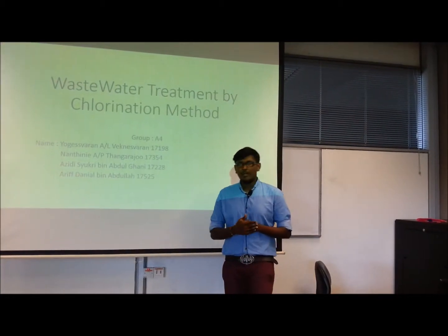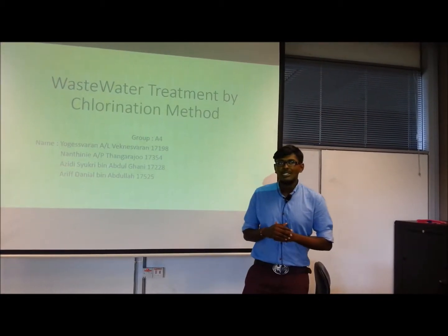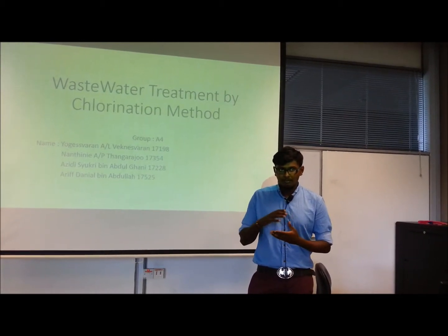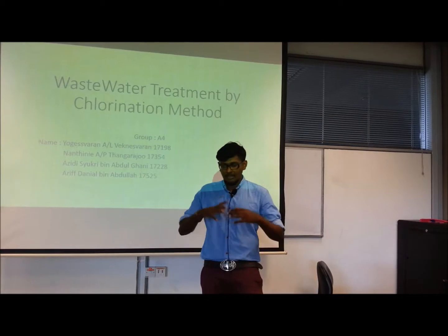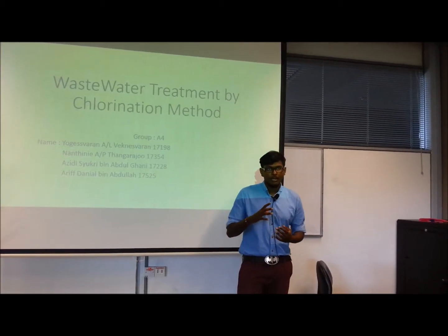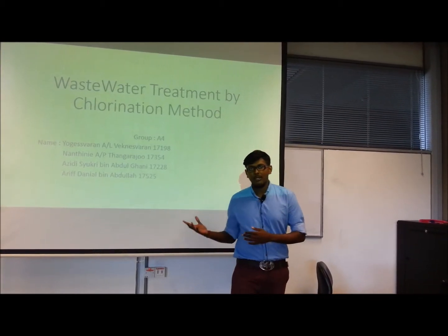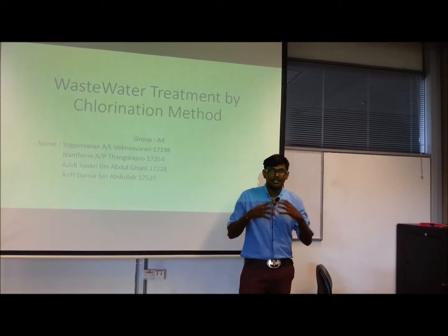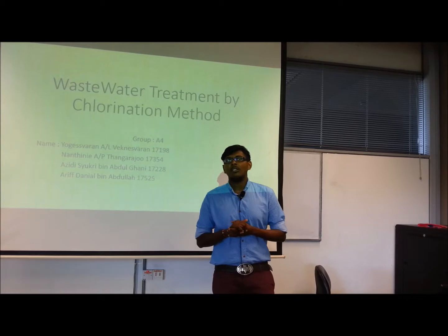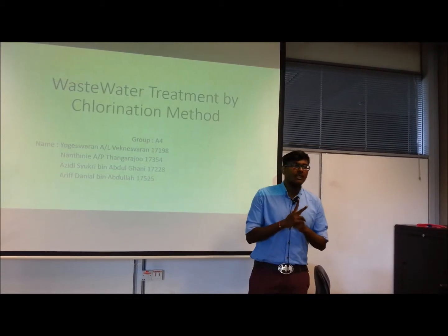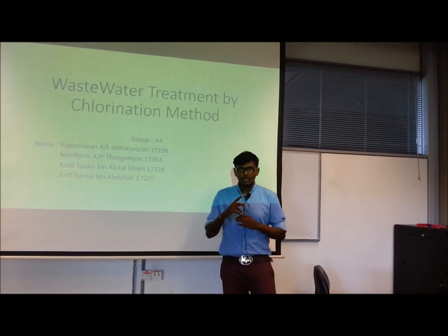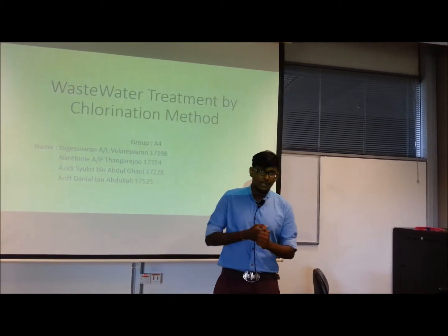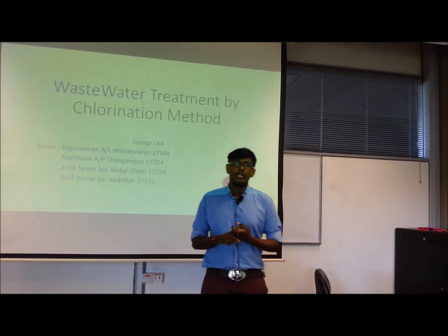What do we mean by residence time distribution? Residence time distribution is the amount of time a chemical fluid spends in a reactor to be reacted and produced away from the reactor, so the amount of time it is inside the reactor. In the RTD method we use two types of input, the ways of giving input into the RTD. One is step input and the other is pulse input.